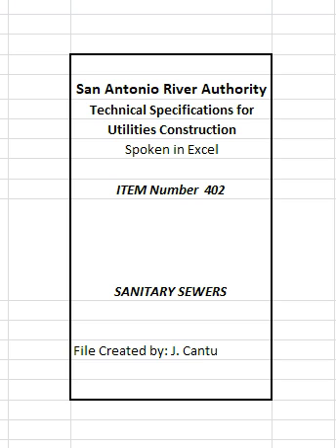The minimum radius for the type of sewer pipe used shall be as recommended by the manufacturer or grader and approved by the engineer. Before leaving the work unattended, the upper ends of all pipelines shall be securely closed with a tight-fitting plug or closure. The interior of laid pipe shall be kept free from dirt, silt, gravel, or foreign material at all times. The interior of pipe shall be cleaned of all foreign material prior to final acceptance of the line. All pipe in place must be approved before backfilling.